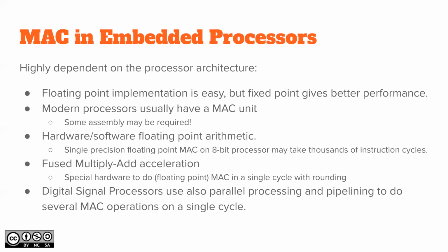If you go to software floating point arithmetic with single precision floating point on an 8-bit processor, it may take 1,000 to 2,000 instruction cycles to operate.